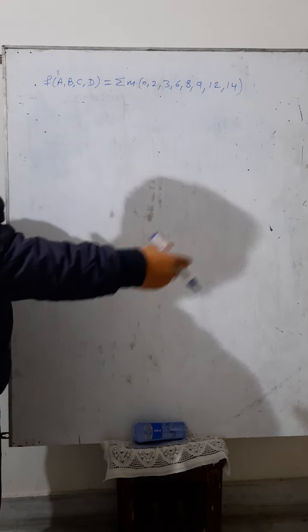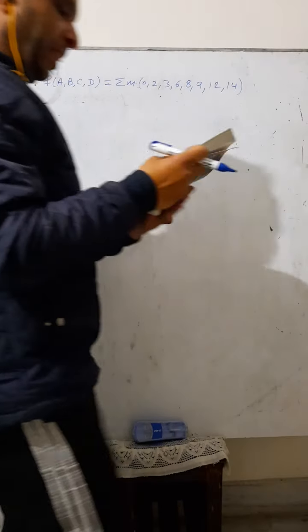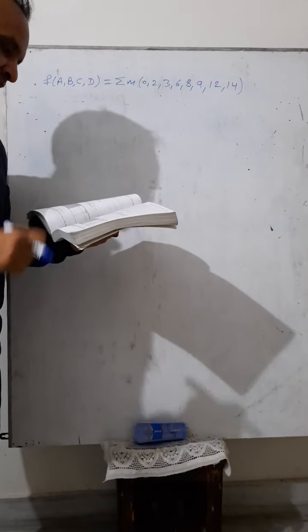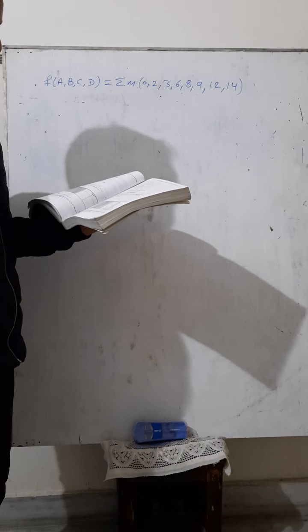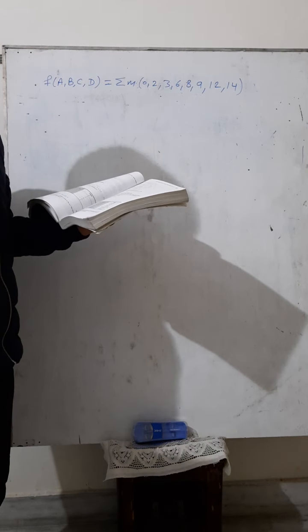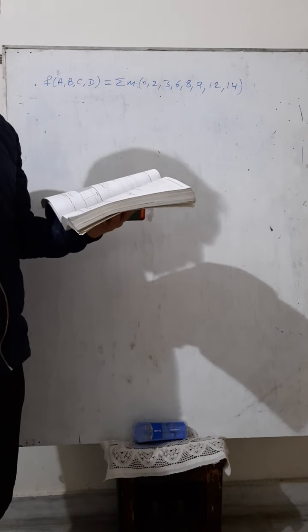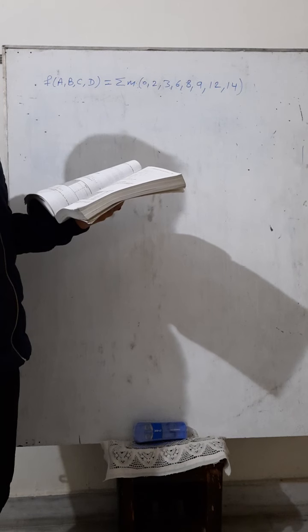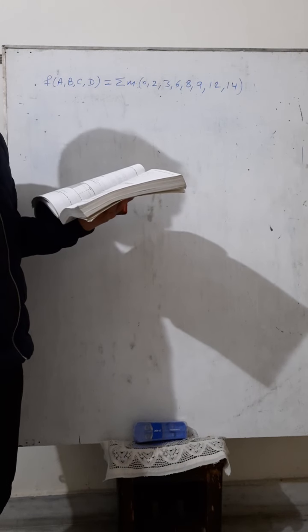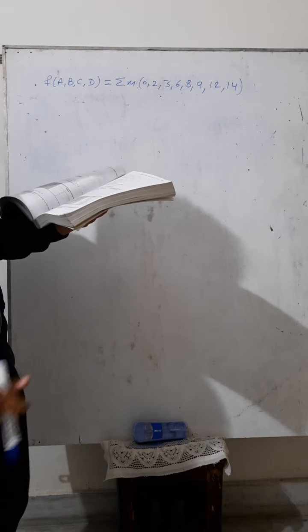There are many types of ICs already available in the market, and a complete table of these ICs is given: 74152 as the 8 is to 1 mux, and 74150 as the 16 is to 1 mux. And 74157, in this IC there are quad 2 is to 1 muxes.